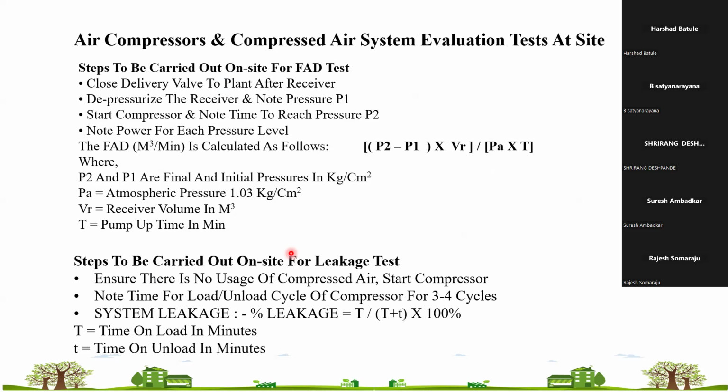Many times volumetric efficiencies are not asked, or if asked, they will provide the compressor displacement formula, because it is hard to remember and there are multiple terms: the diameter of the cylinder bore, the cylinder stroke, then the compressor speed in RPM, whether it is a single-stage compressor, a double-acting or single-acting cylinder, and the number of cylinders.